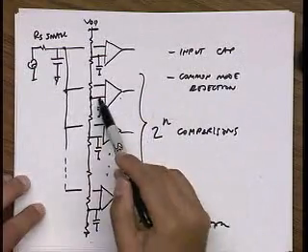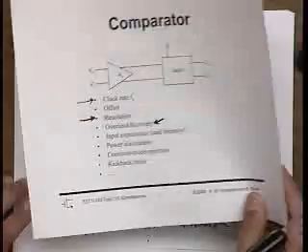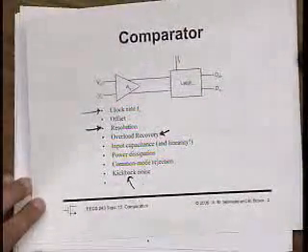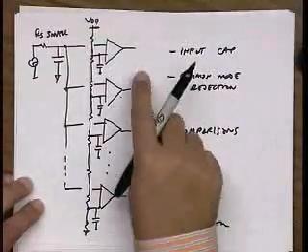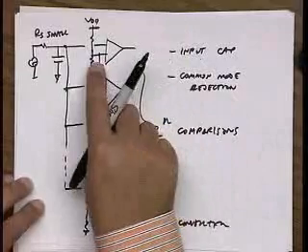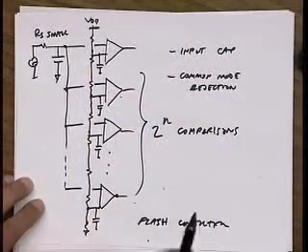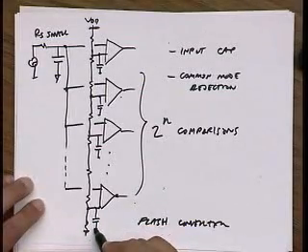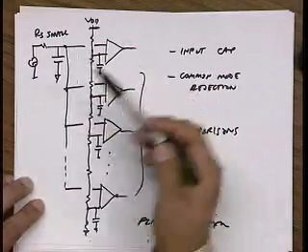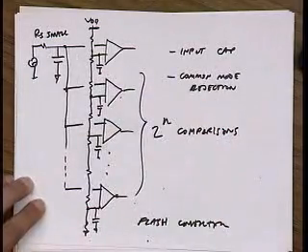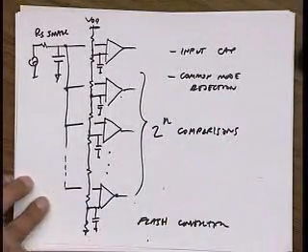But what if, due to kickback, which we haven't talked about yet, what happens is that as these different amplifiers make decisions, there's capacitive feedback back onto this node. So you get transient voltages on these nodes. Yeah, I should have mentioned this. Otherwise, it doesn't make sense. These transient voltages on these nodes take an RC time constant to discharge, right? And I want those to disappear as quickly as possible. Otherwise, I'm going to make the wrong decision. Yeah, thanks for bringing that up.